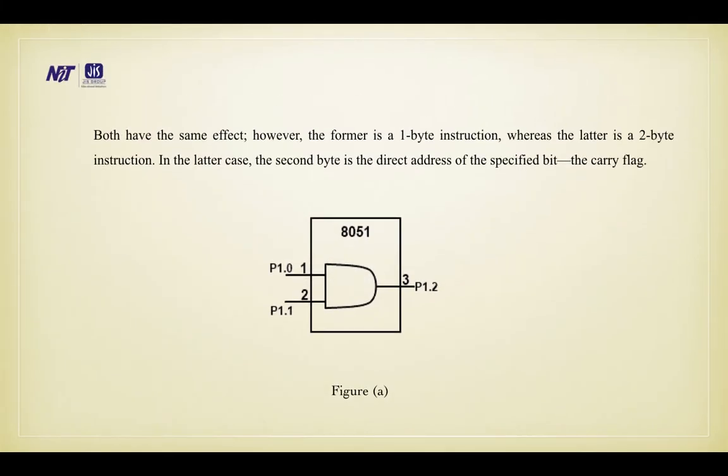Both have the same effect. However, the former is a 1-byte instruction whereas the latter is a 2-byte instruction. In the latter case, the second byte is the direct address to the specified bit with a carry flag.